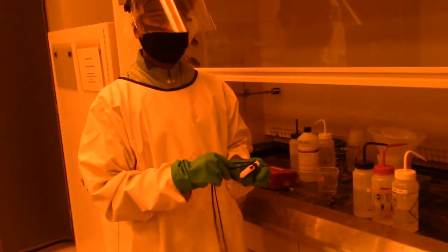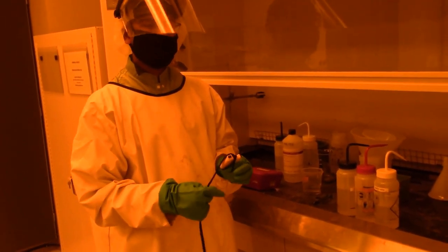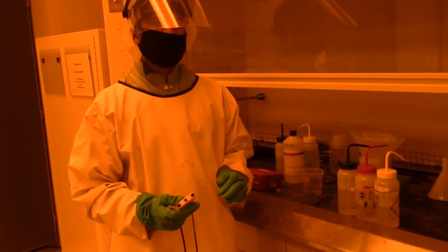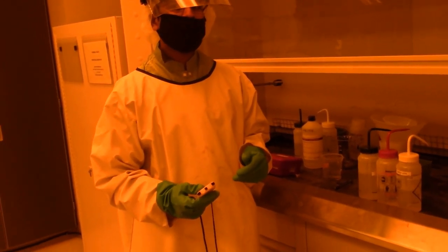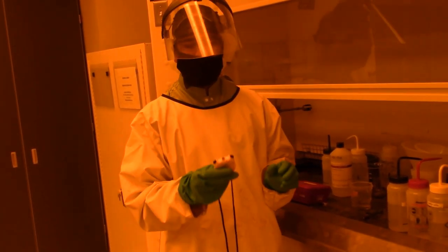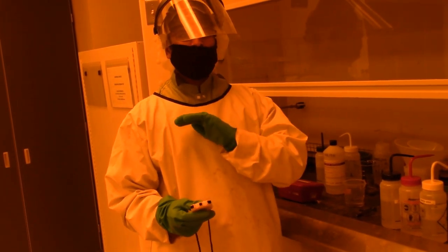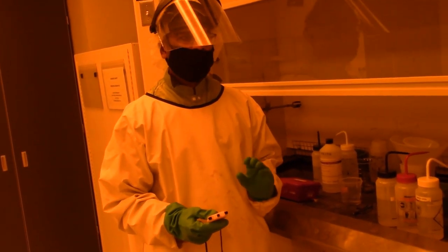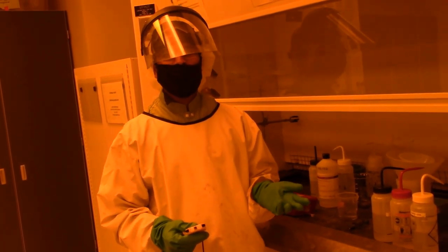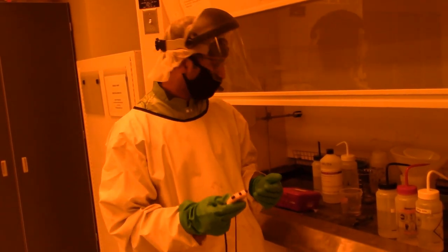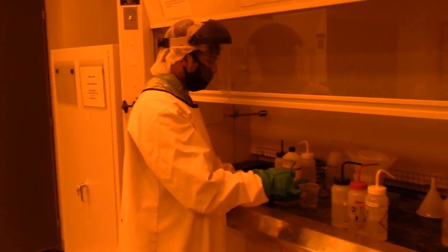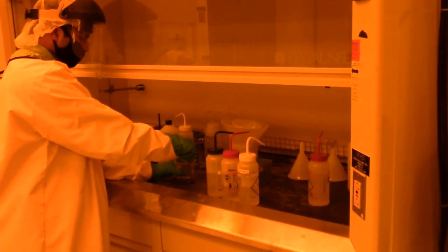Now, the oxide thickness is around 95 nanometers that we measured using ellipsometry. The etch rate for the hydrofluoric acid is supposed to be around 90 nanometers per minute. So we'll go ahead and etch it for at least 1.5 minutes, so it completely removes any oxide, and we can make a good metal contact immediately using thermal evaporation of that. Okay, now that it has 1 minute 30 seconds, we can go ahead and take the wafer out.